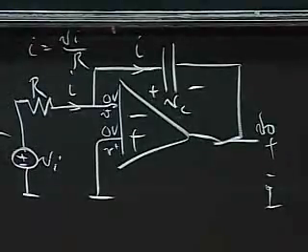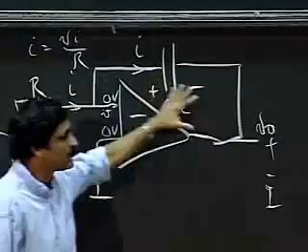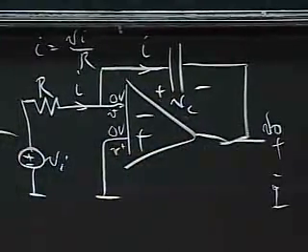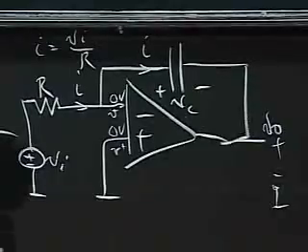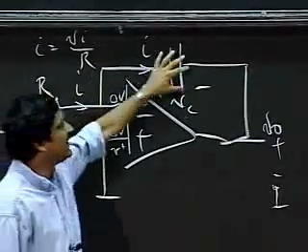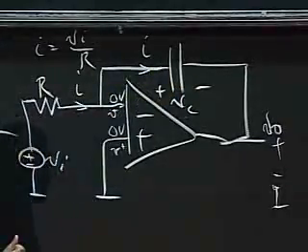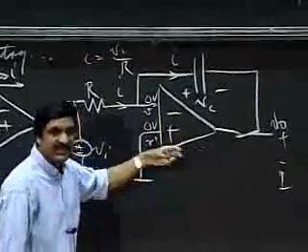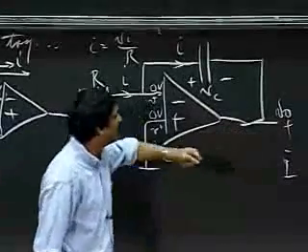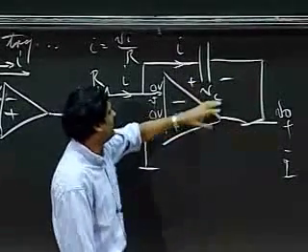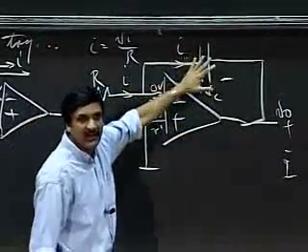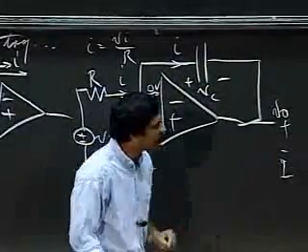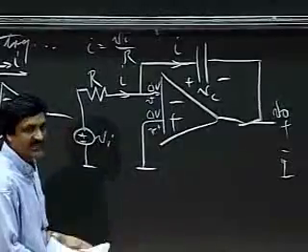Okay, so this is another very common building block. Remember this. Most of the circuits we will be seeing with op-amps simply involve something here and something here. And the output in this inverting connection is the input times, if it's a resistance, simply R2 divided by R1. When it's a capacitor, I get the integral form looking like this. Yes?